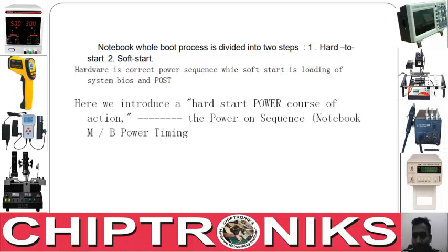So how does a notebook start? It can be divided into two parts. One is the hard start and another is soft start. Hard start is when the entire component of the notebook motherboard receives power, but still it's not working because it has not received logic, the way it has to operate, and the way it has to operate it can gain from a BIOS, right? You can call BIOS the logic, whereas in the first case the hardware gets started, and in the second case logic gets started.